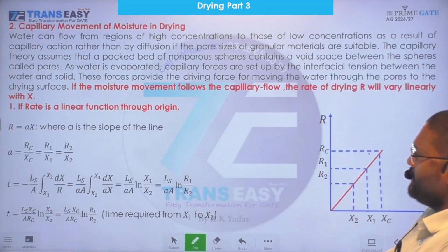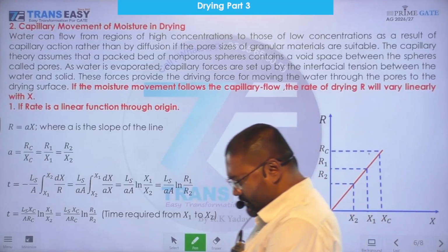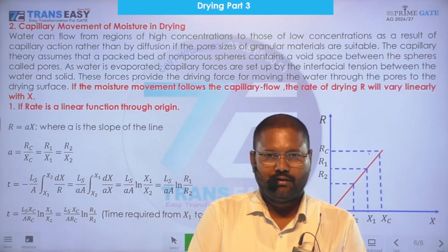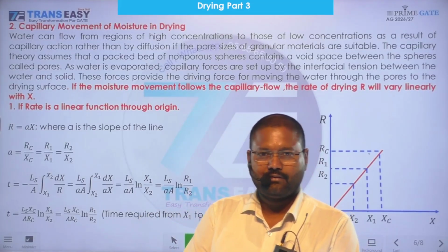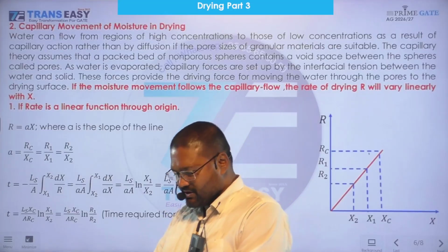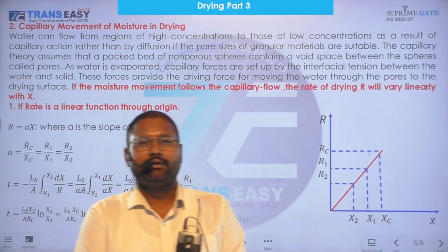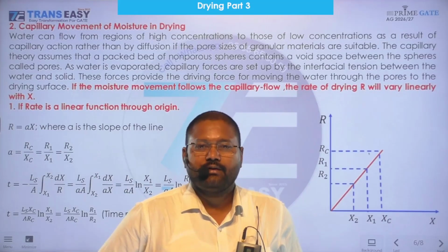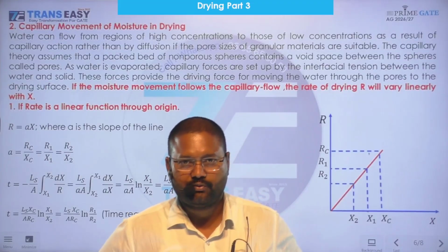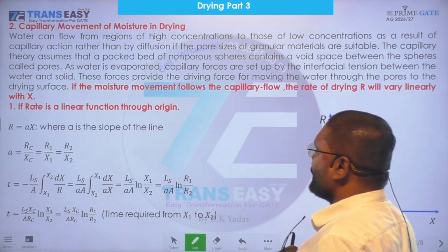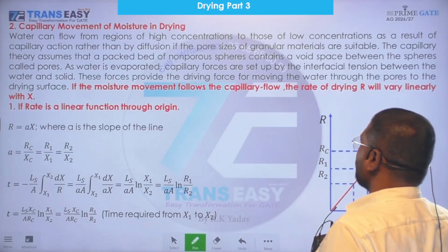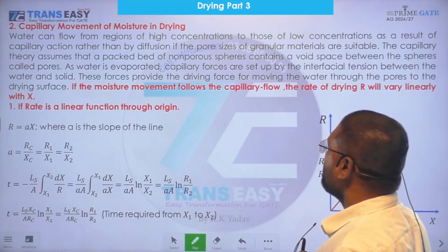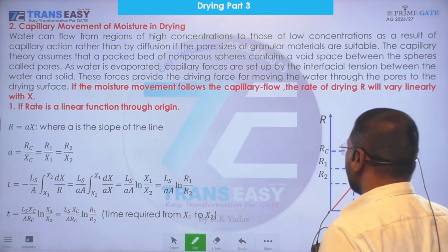Dear friends, if drying in falling rate drying period is guided by capillary action, right? So for such problems we are going to calculate drying time for reduction of free moisture content x1 to x2. Water can flow from regions of high concentration to those of low concentration as a result of capillary action rather than by diffusion if the pore sizes of granular materials are suitable.